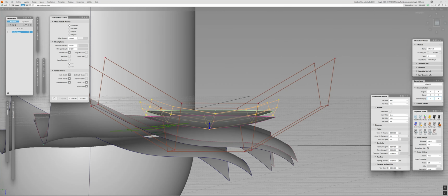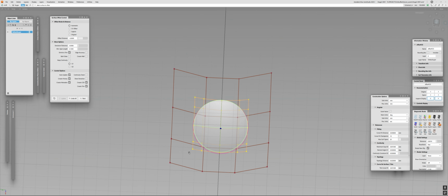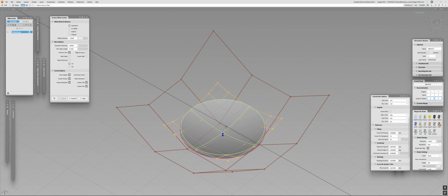So it reparameterized it to the edges, and it sometimes becomes very useful, especially if there are a lot of objects and it's difficult to pick the proper one, or you need to do some UVs or some parametric modeling, doing patterns and stuff like that. The fact that the surface is contained within the bounding box can be pretty useful. Now, this is not for everyone. I would say in 80% of the time you don't even bother what's happening with them, but in the situations where you need UVs or you need